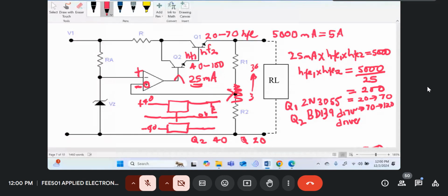So we've got a sampling element with a variable. I don't know, when time is up, I tend to make mistakes. So these two pots are synchronized. They're ganged in one. So this becomes here 0. So here maybe you can get plus 15 volts. Here you can get minus 15 volts. So you've got an identical circuit. Let's call them circuit A and circuit B. Circuit A is like the one we're using today, and circuit B is identical to circuit A, only we use PNP transistors instead of NPN.